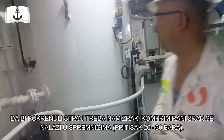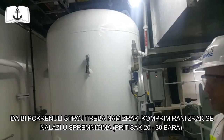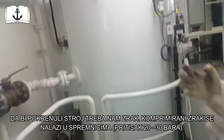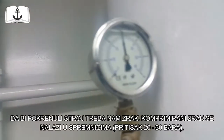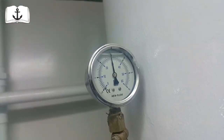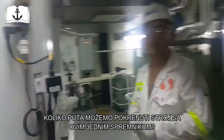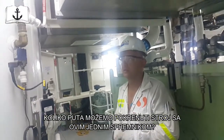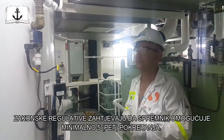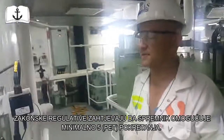Okay, start from the beginning. To start an engine, you need air, right? This is compressed air, correct? Yes. You need between 20 and 30 bar. How much pressure do you have inside? Of course 30. I glued this arrow for you. You have always 30. So we have 30 bar inside, and how many times can you start an engine with this? The requirement by law is that you must have 5 starts, but we have much more.